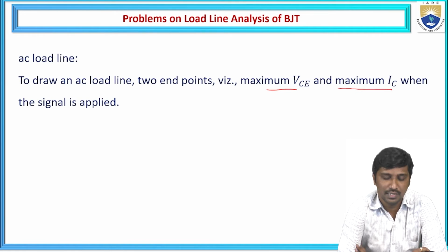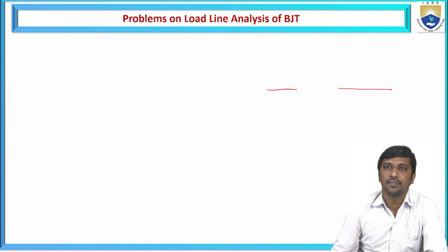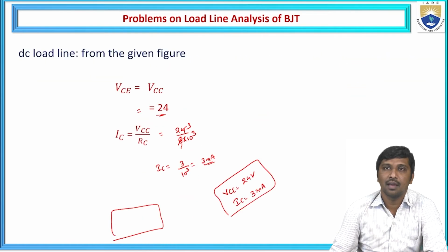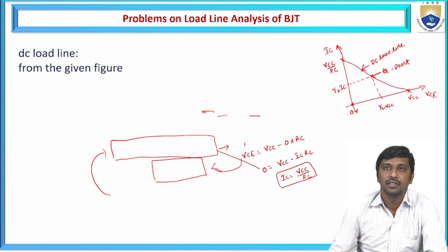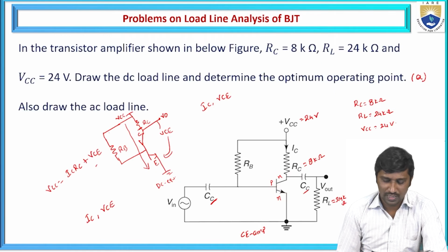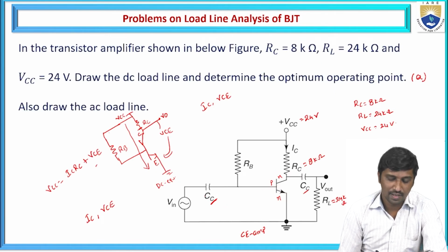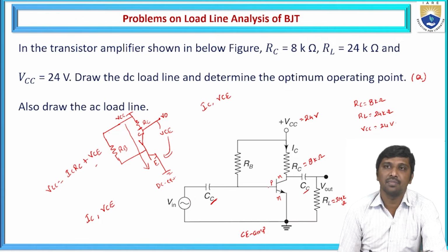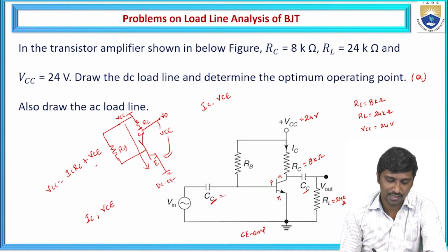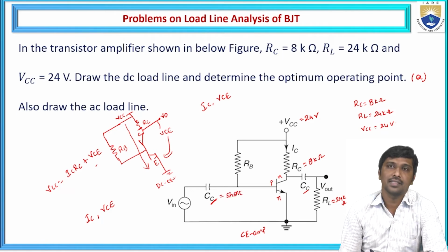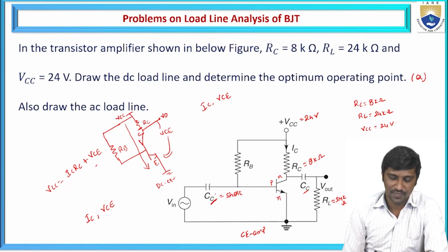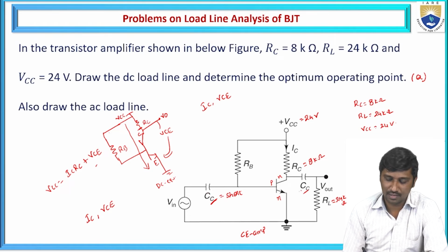Before going to the signal, let us observe the circuit for the given amplifier analysis. When the AC signal is present, meaning the input signal is passing through the input of the amplifier circuit, the coupling capacitors act as a short circuit. Why? Because the capacitor allows the AC signal. Hence, the input side capacitor and output side capacitor act as a short circuit.